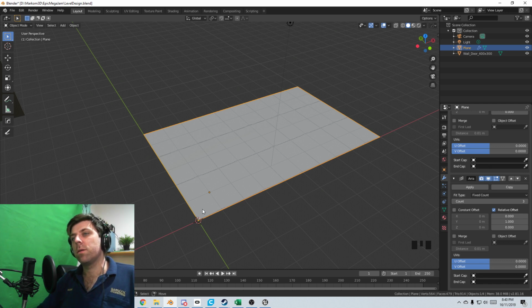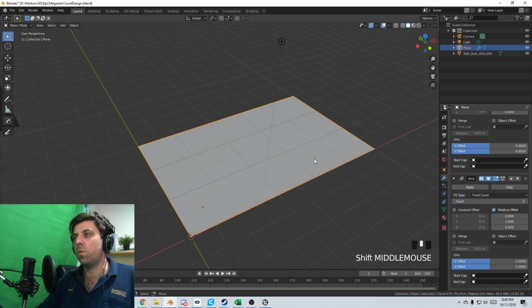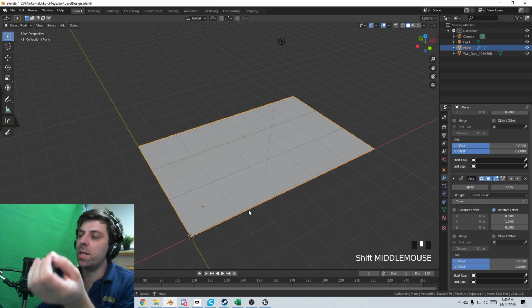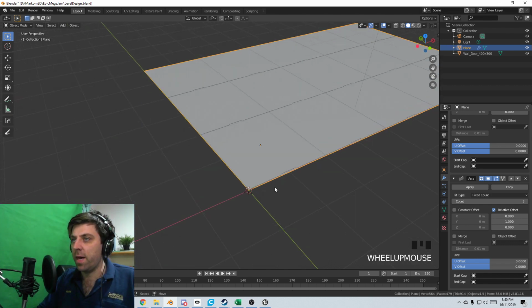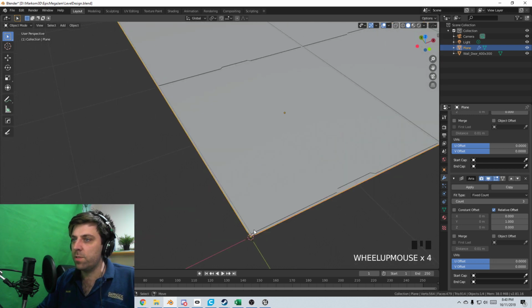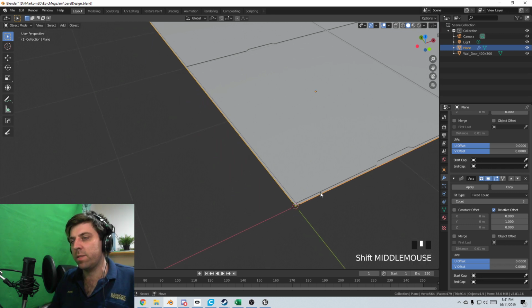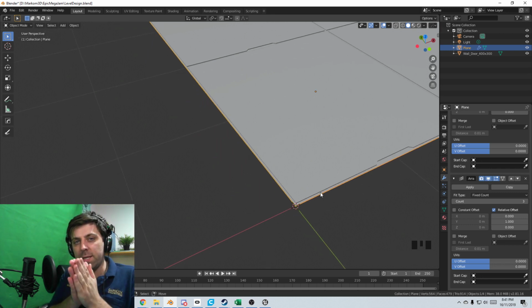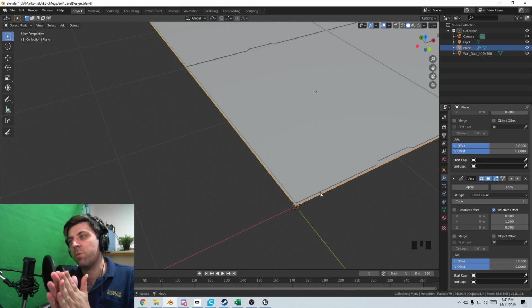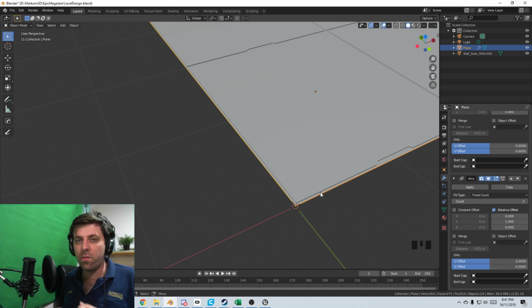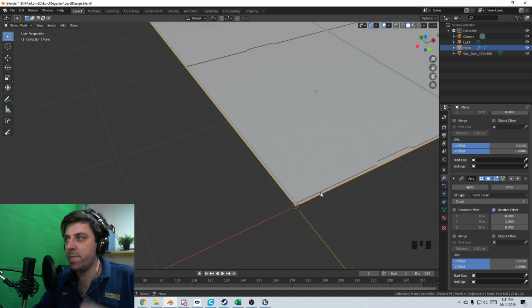Well, actually, technically I could use this for all the floors, but I don't want to, because the wall is not going to be on 0, 0. If I have a plane and a plane sitting on top of each other, they're going to intersect with each other. So I'm going to offset it a little bit, and that way I can put in a door frame. When I have doors either sliding or opening, specifically if they're sliding, they will slide into the walls, hiding a little bit.